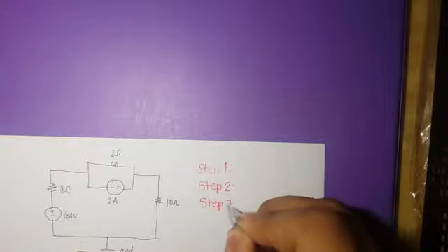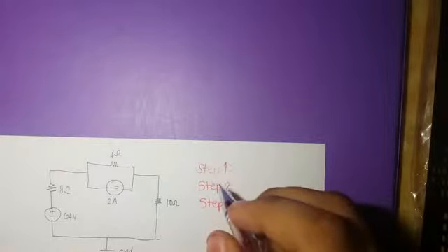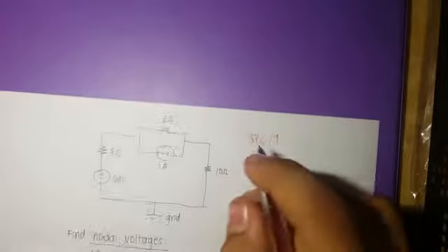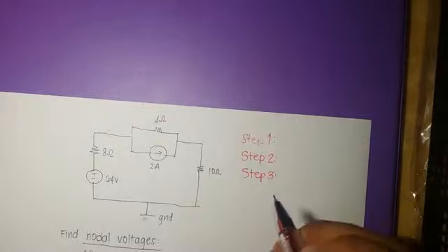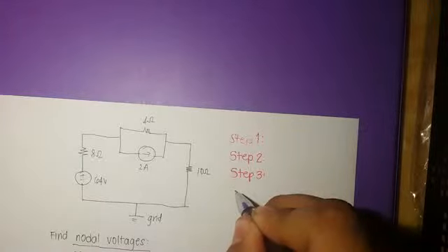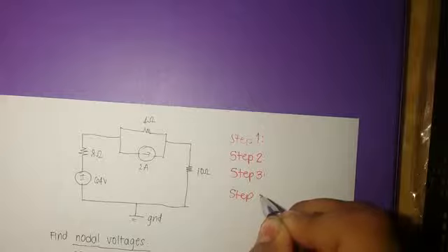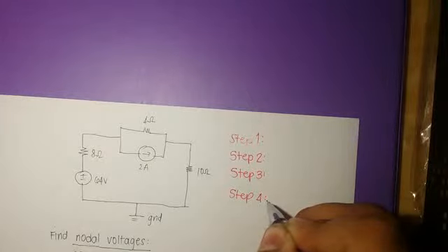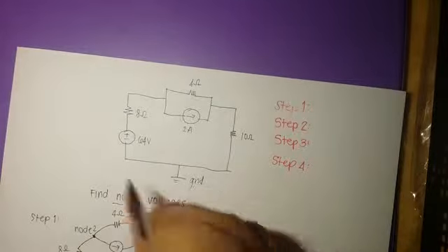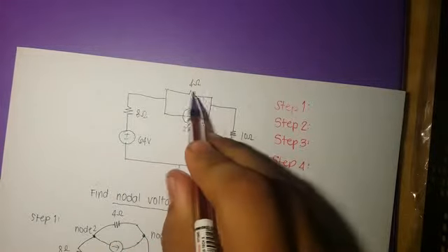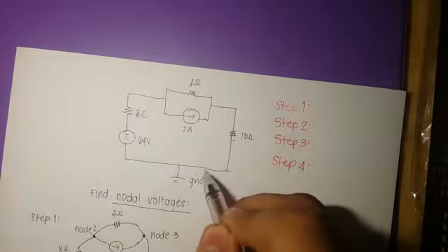Apply Kirchhoff's current law at each node except the reference. Assume that all unknown currents leave the node for each application of Kirchhoff's current law. In other words, for each node, don't be influenced by the direction that an unknown current for another node may have had. Each node is to be treated as a separate entity, independent of the applications of Kirchhoff's current law to the other nodes.